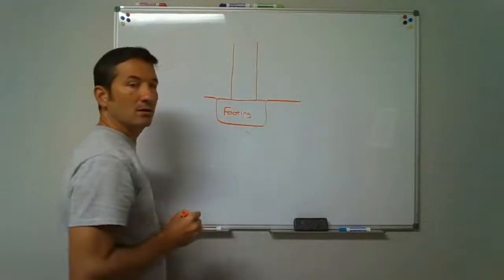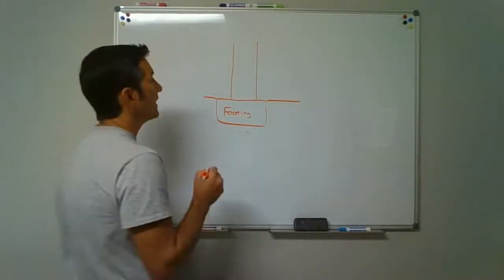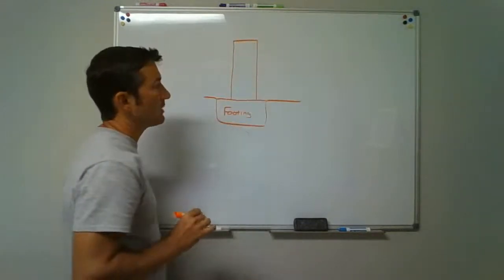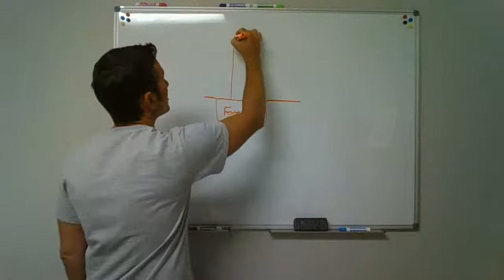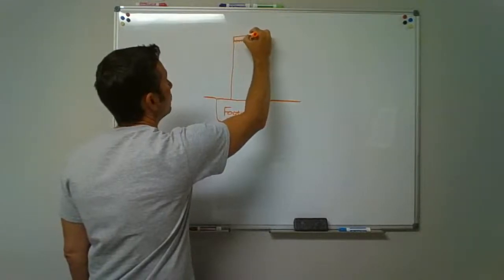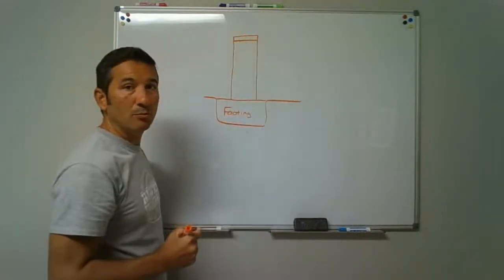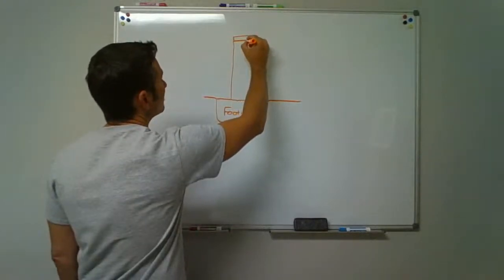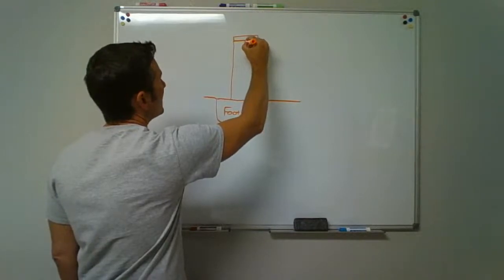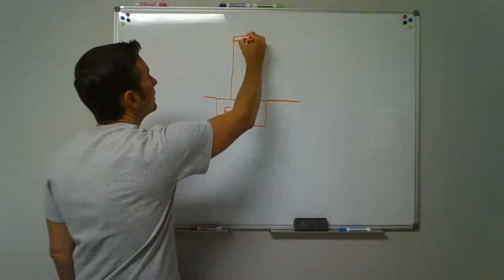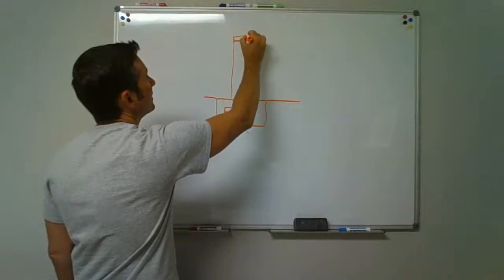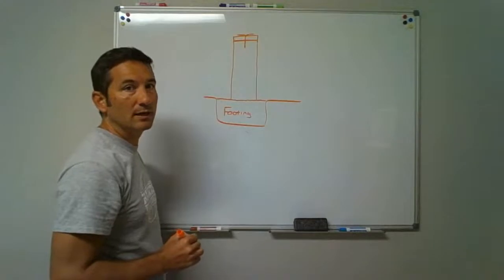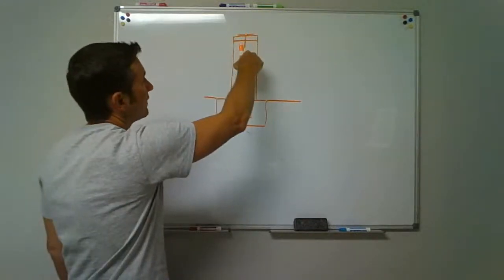There comes up the block and brick wall for the foundation, and then we build up on top of that. When you were underneath the house and looked, you saw a wooden sill plate tacked onto there. Holes get drilled in that, and there are straps anchored down into this foundation wall. Those straps come up with little tabs that they bend over and nail down, anchoring the sill plate to the foundation wall.